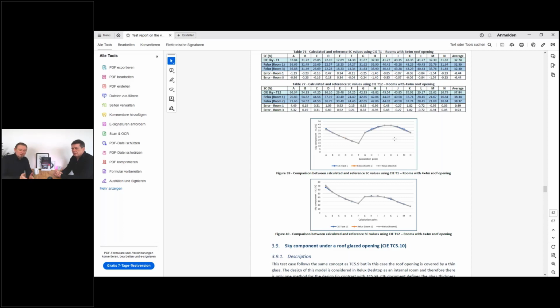And even the measuring has a failure, so the calculation is also in a way bound to this, and there's also a failure. So you cannot precisely hit down a specific level. You have always tolerance, and you have to deal with it as a lighting designer, and need to communicate it. You need to say, okay, I have not hit the value there. Keep in mind this is plus minus 10%. In single points, even higher. So it's just the average, which is 10%.